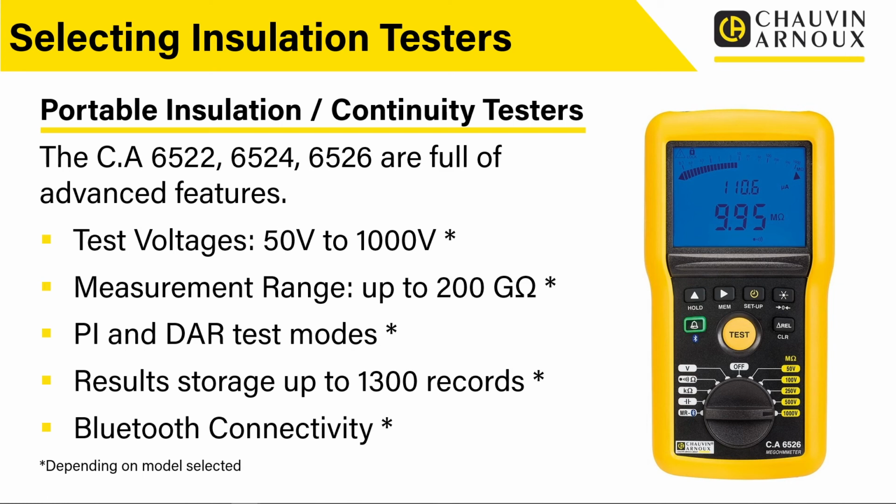Now, what we also start to see is some of the more advanced test sequences coming in here. So we've actually got the ability to do some tests that you'd expect to see on the higher voltage testers. For example, we've got the PI test, the polarization index test, and the DAR test. That's included within these testers, particularly within the 6526 and I think the 6524 as well.